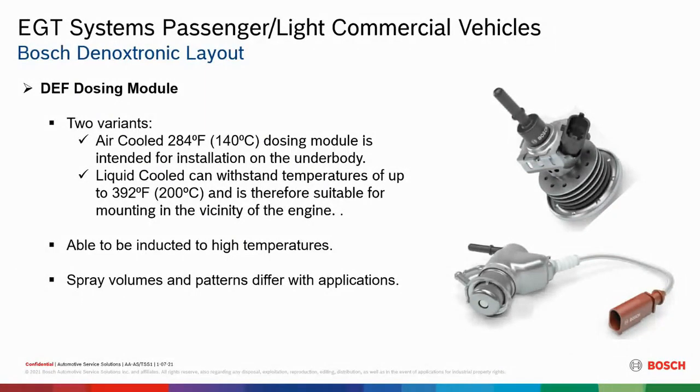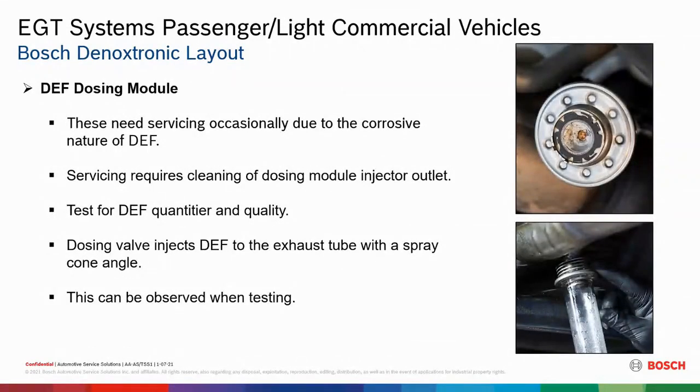So it's able to be inducted into high temperatures. The spray volumes and patterns are all different from manufacturer to manufacturer. And then occasionally these do need to be serviced. So during a service interval, it's not a bad idea to pull these off and check them. Due to the corrosive nature, they build up corrosion right around the inlet and outlet of these injectors. So servicing is required at certain times.